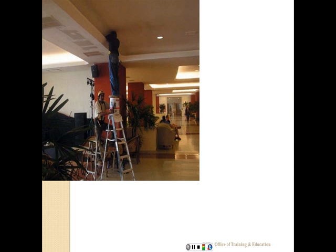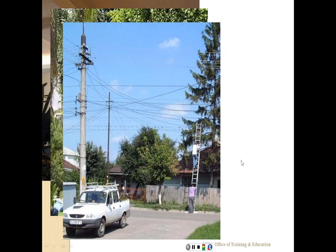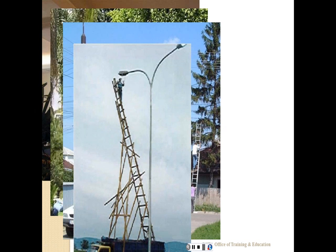Here are some violations about the use of ladders. We have several violations here. First of all, he used the top of the ladder. Not only that, he placed something on top of it, so it's a double whammy. So obviously that's a clear violation. What can I say about that? That definitely is a huge violation. Okay. Resting the ladder on top of the power lines. How genius. No comment. Does that look like a ladder that you should use in construction? Or anywhere?